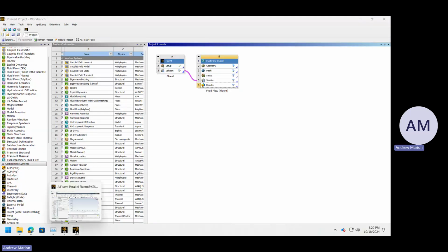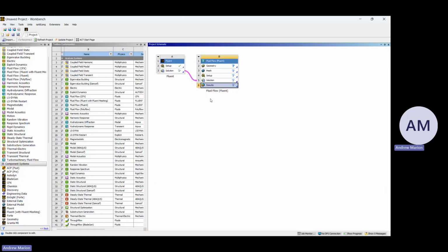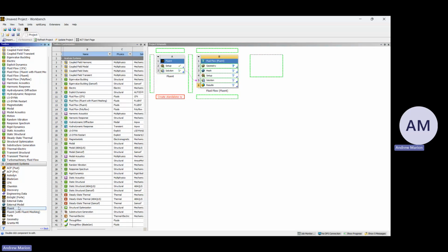Make a surface in Fluent, yeah. So you can drag. And this is also a cool thing about Workbench. You can have a bunch of simulations. So let's say we did this at 0 and I want to do it at 10. You can drag out another Fluent. Angle of attack specifically, 10 degrees angle of attack.